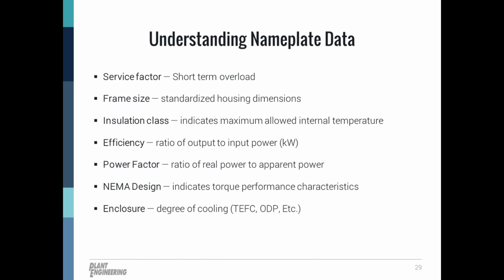All right, if your motor is on an application where the torque fluctuates, it is always a good idea to have a motor with a higher service factor. This will allow the motor to withstand a short period of time where it can be overloaded by the service factor multiplier. Meaning if the motor has a service factor of 1.25, the motor can run at 125% of rated load, while keeping in mind that overloading leads to higher currents, which in turn leads to higher motor temperatures. Always monitor the motor temperature closely to eliminate any chance of shortening the life of the motor.